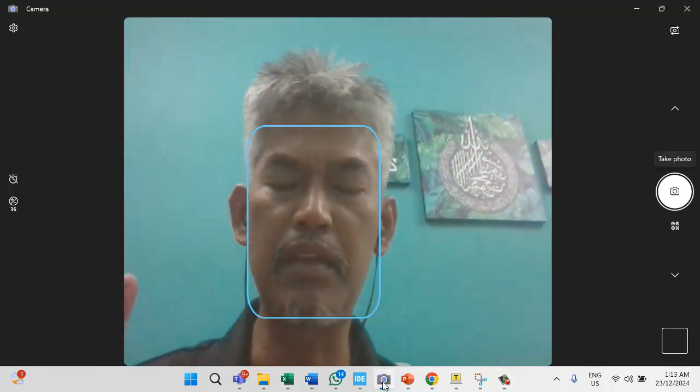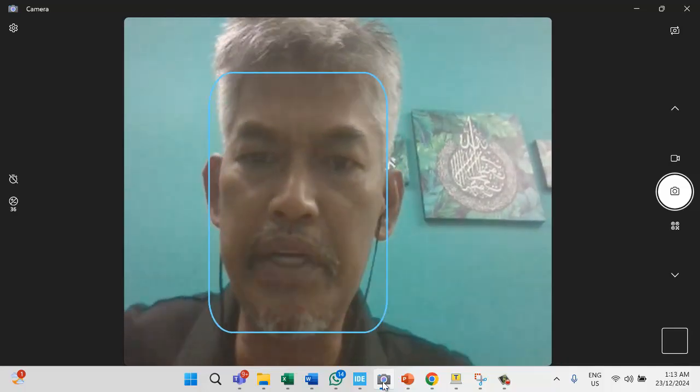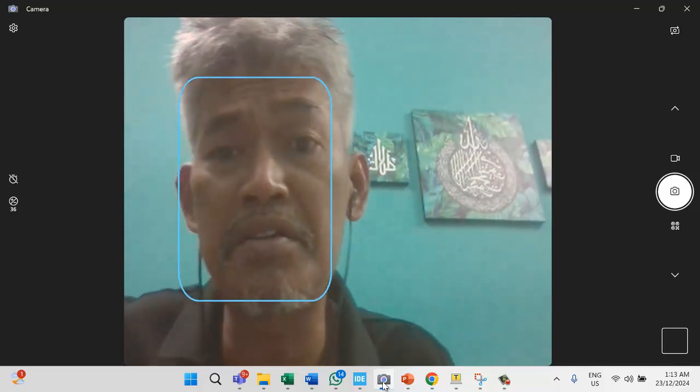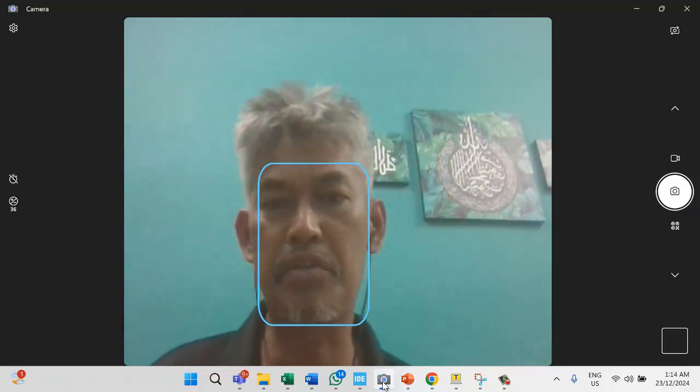Hi, I'm Smell. Today in this video I will show you how to write code for the timer in counter mode. Of course, I will use the interrupt.